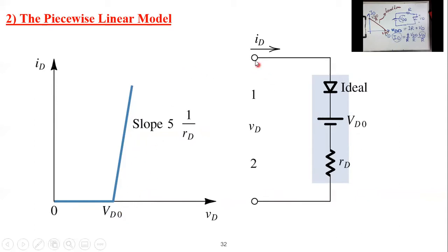And if you put in these two terminals V forward equal V_D0, then you will find that V_D0 minus V_D0, then the current again is equal to 0. So the terminal voltage has to be greater than V_D0, the built-in potential, so that you can have a current here. Otherwise, you will not have a current. So this will consider the piecewise linear model.